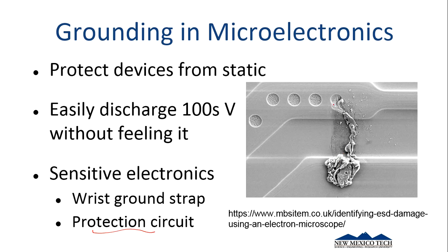I don't 100% know what's happening here because this is a proprietary piece, but what I could imagine is that this is a piece of copper and this is a piece of copper, and maybe this is a piece of copper, and we basically blasted this thing across and maybe shorted out across this piece here, because when we discharge hundreds of volts into something through just a little tiny area, we can heat it up really quickly to thousands of degrees, and basically this metal can vaporize even. That's what some of this splatter is all the way out here, all these little dots.